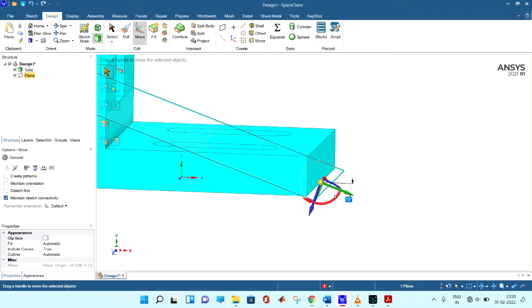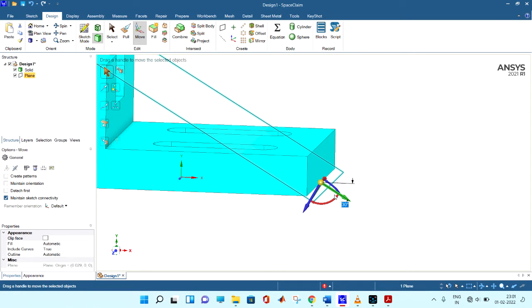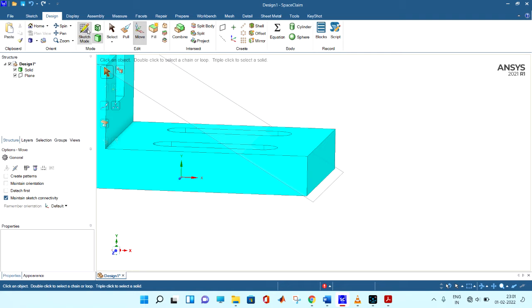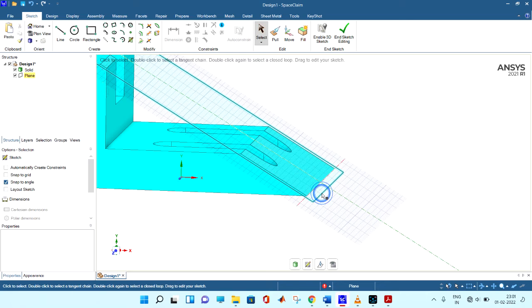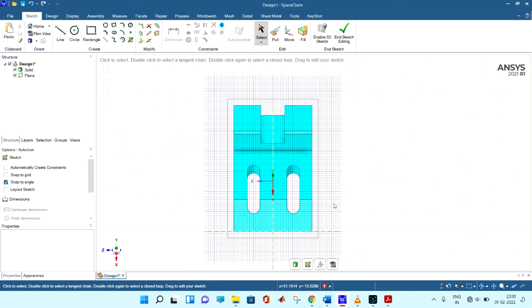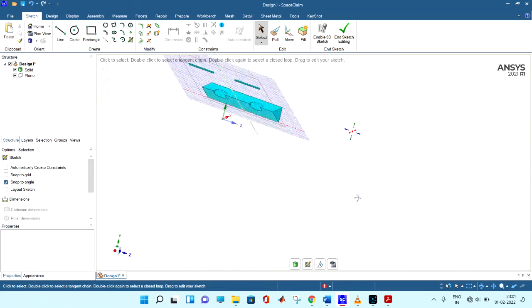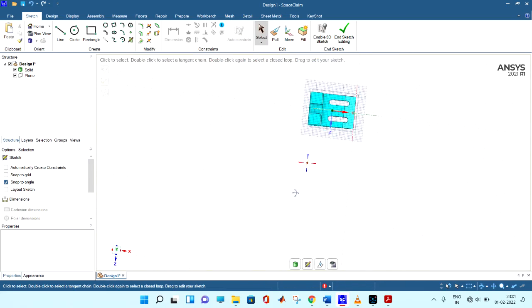Know that we have to rotate 30 degrees with this. Okay, when it is showing with respect to this axis, can you tell me how much it should be with respect to this axis? That is 30 degrees. It has moved 30 degrees. That's our plane ready. Now we go into sketch mode. I have chosen this plane. Then I say okay, plane normal. Okay, I don't want it in this face, I want this plane like here, so I'm just clicking the Y.